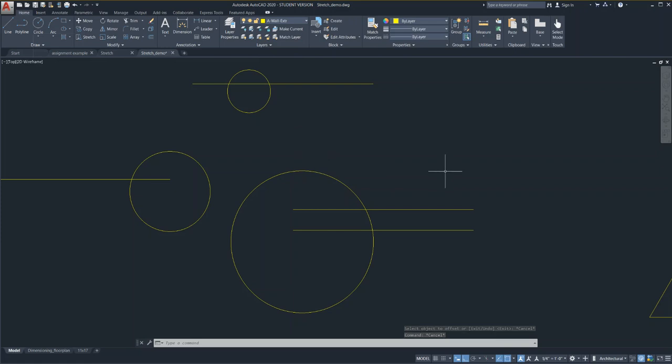I can also hit TR, okay? And the very quick way of using this command is to type in TR with 2 enters. And it's important that you hit enter twice, otherwise the quote quick way won't work. Okay, so I'm going to type TR, enter, enter.